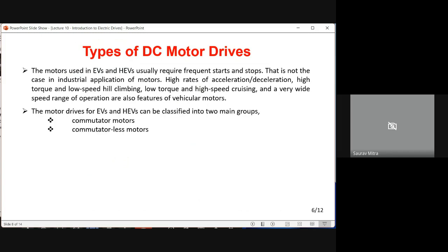So we found that there is mainly this brush. Brush is actually taking the external static DC supply because it is coming from a static voltage source, and the armature is actually a rotating part. So that is a very important thing, that is, who is taking this static supply to a rotating armature. It is actually happening through a brush commutator arrangement. So external DC supply is given to the brush first, and the brush is connected to the commutator. Commutator is taking the supply to the conductors.